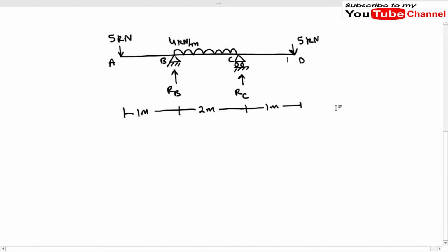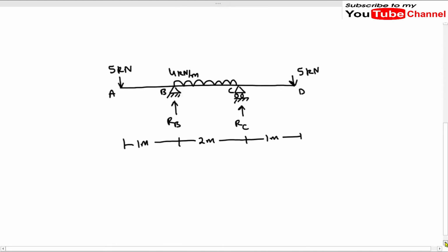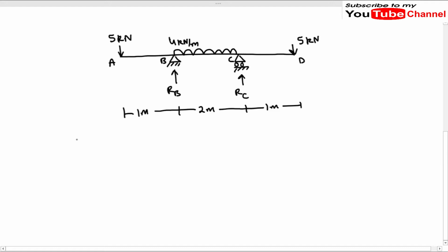So this is our beam. Now we have got the reactions at B and C, and we will proceed with our solution further. Here I have drawn the beam again. The first equation which we write for Macaulay's method is EI d2y over dx square is equal to Mxx, where Mxx is the bending moment at section xx.